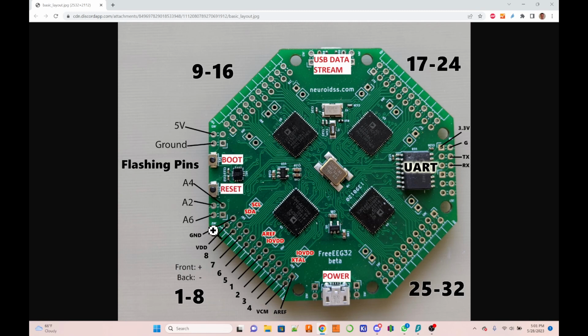Where to find the pins, and again, if you want to make a linked ears type of connection, then you usually take all of the negative pins of the channels and interconnect them, and then using 2 ear clips, one to the left ear, one to the right ear, then you would have a linked ear setup, and then all the other channels, however many you use, they go to the different positions. The plus terminals, they go to a position on the head, you know, the 10-20 system, or whatever you do.